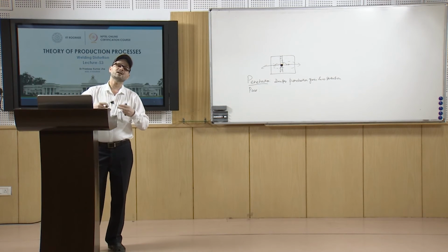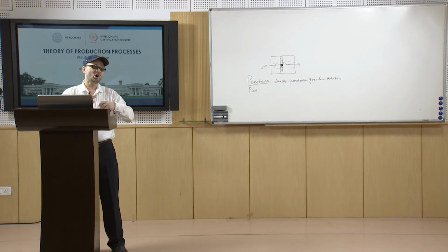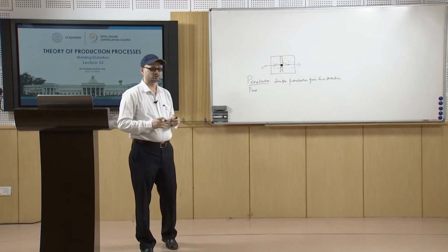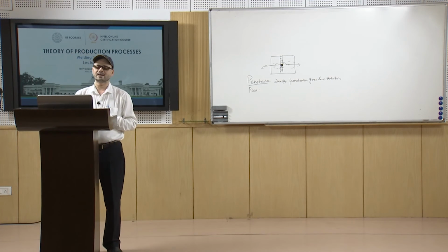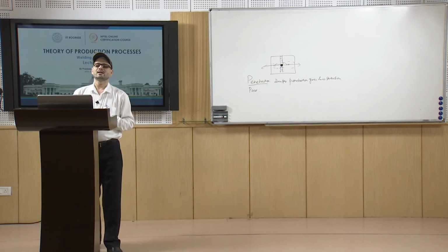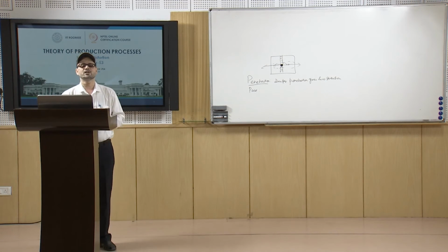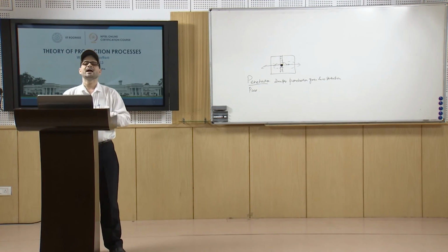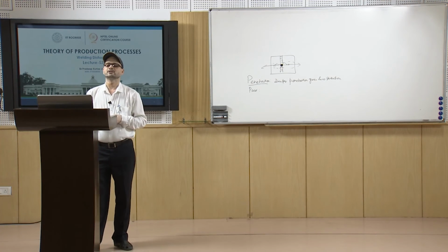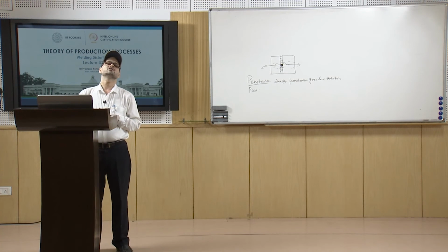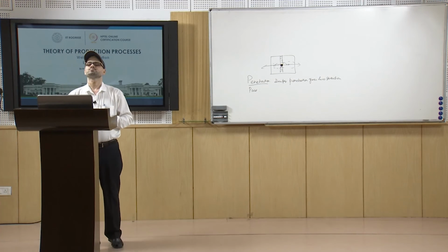Then the thermomechanical properties of the material and the welding processes, all these are the processing parameters which affect the amount of angular distortion that the material will be subjected to. Like the parameters of the welding process, then again comes heat input per unit length of weld, and distribution of the heat source density. So, these are the parameters which affect the extent of the angular distortion to which it will be subjected.